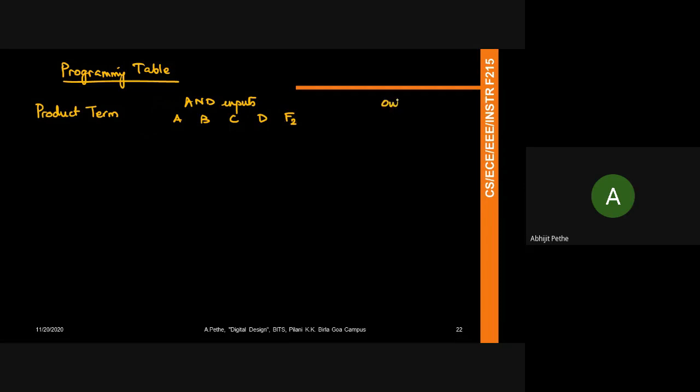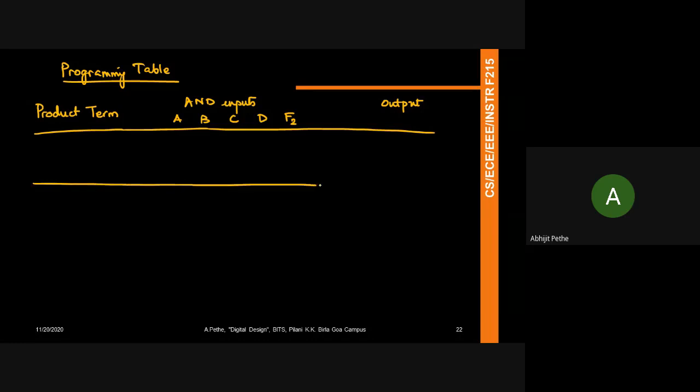And that's all there is in programming. The output really is just a combination of whatever you're doing here. If you can think of the product terms, you can break them up as groups of 3, because we know that the output has to be a sum of at the maximum 3 product terms.